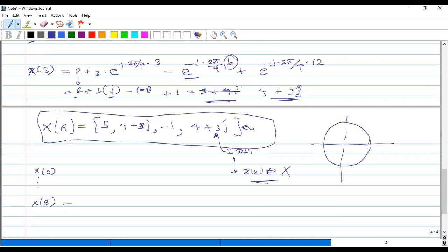You can use this circle, the unit circle. Then you have to calculate the end points. So you are doing 8-point, so you are going 2π. You should have 2π by 8 angle separation, that means π by 4, 45 degrees. So after 45 degrees, we have 1 point.